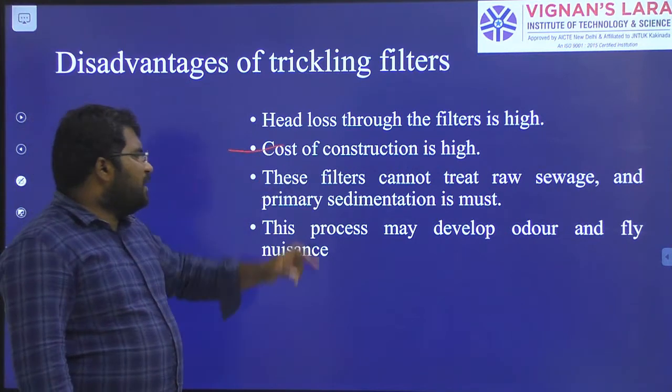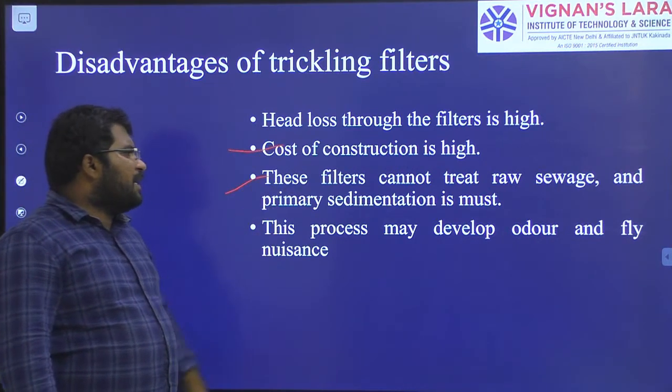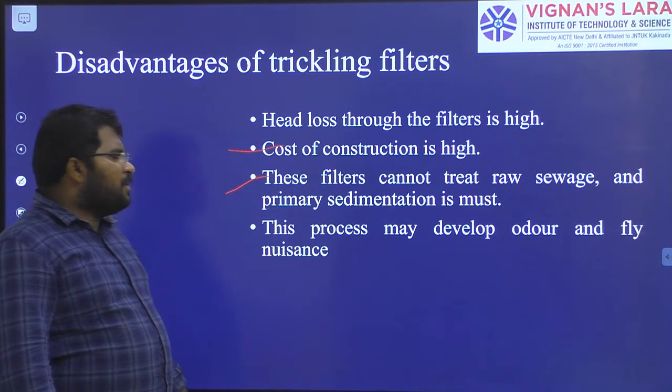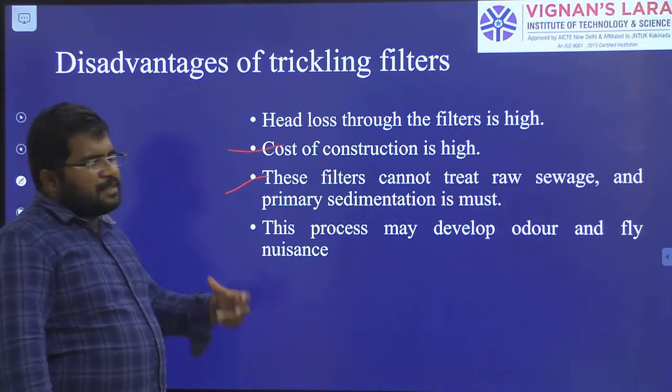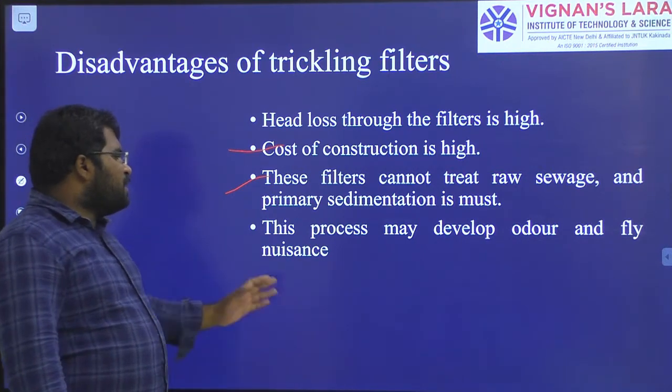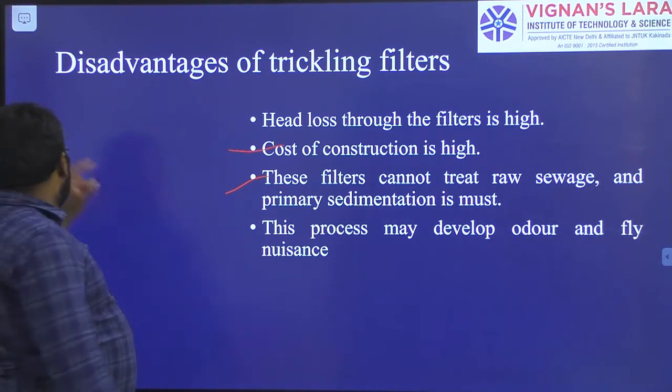Next, disadvantages. Head loss through the filter is very high. Cost of construction is very high. These filters cannot treat raw sewage, and primary sedimentation is a must. This process may develop odor and fly nuisance.